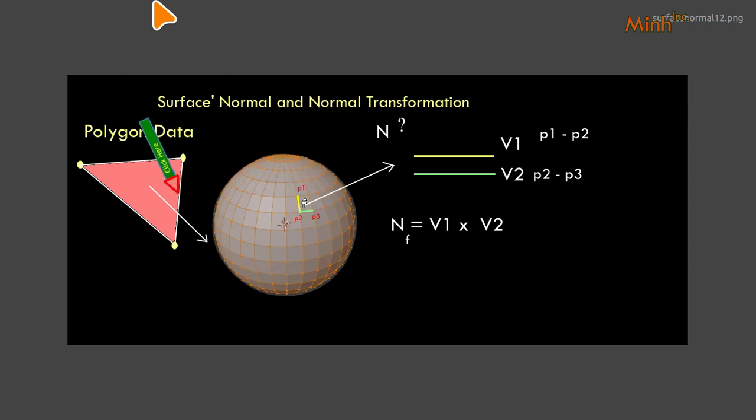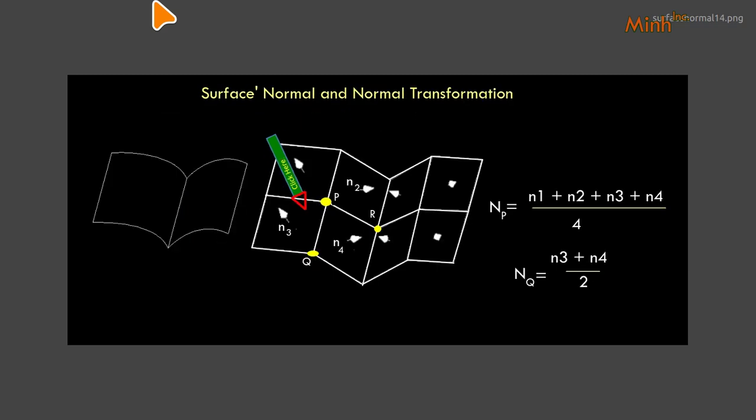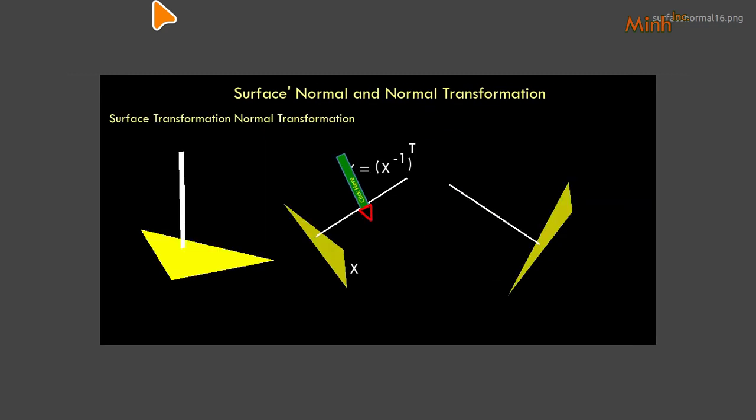Surfaces are of two types. For polygon data, for each facet we calculate vectors and then calculate the normal by crossing them. Then for each point, we average the normals of the neighboring facets. Points can be convex, concave or edge. For convex and edge points we take care of the neighbors, but for concave or deep points we also rely upon the neighbors, so it becomes really smooth.